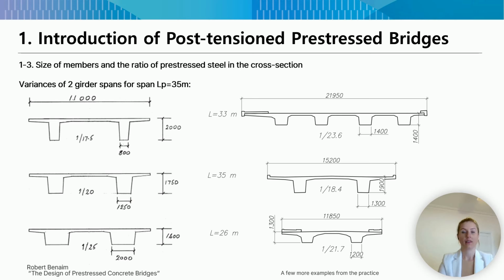The average ratio of span length to beam height can be considered as 1:20. Similar spans of constant height are used up to 45 meters, with an average consumption of high-strength reinforcement of 50 kilograms per cubic meter. The beam width is constant and is determined by the following parameters. First of all, space for placing anchors. Then, compressive stresses from bending moments.